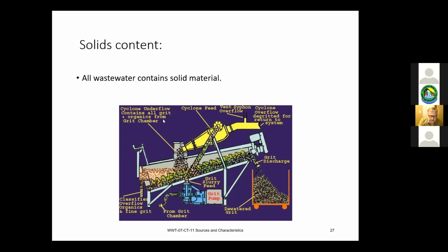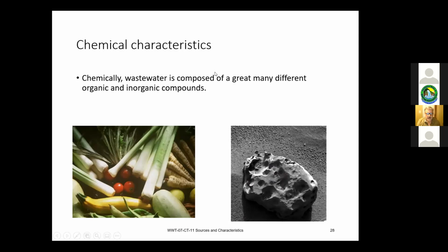Nice. Okay, good. Bar screens, some type of screening facility in advance, is definitely the way to go. Grinding used to be the standard treatment method, but all you're doing is cutting things into small pieces and sending them into your plant, and then there's some magic that happens in a plant, and I don't know how it happens, but the rag balls seem to form together, and I'm quite sure everybody's seen these, especially in a digester, for example. So better off, if you have to do something with it, to screen it, remove it, and get it out of there.